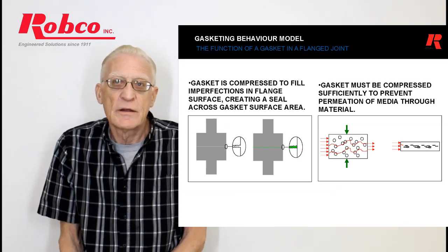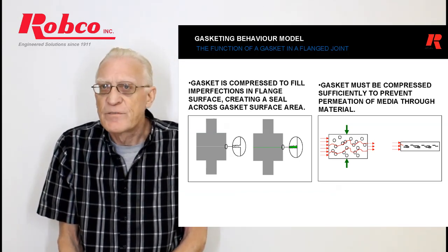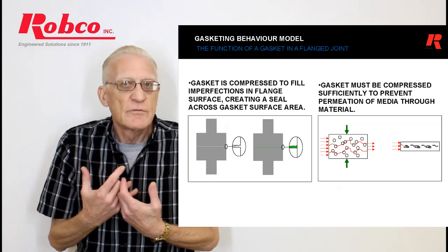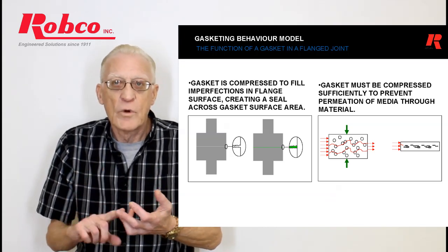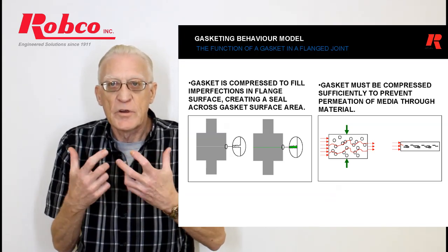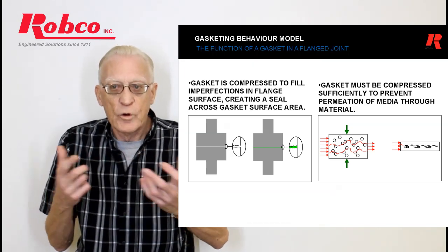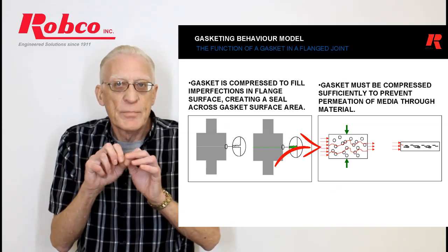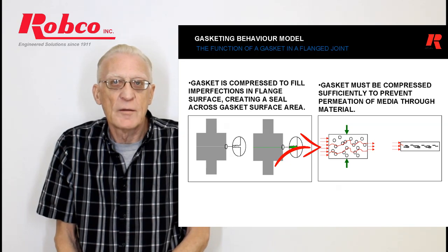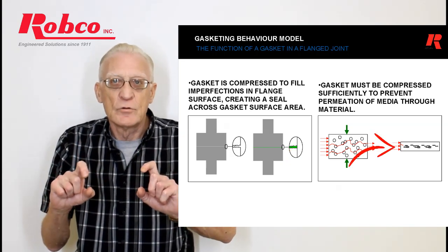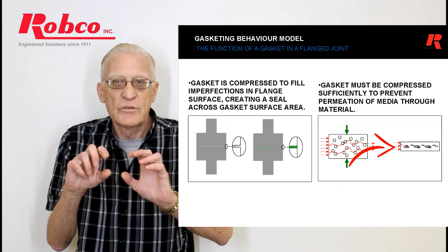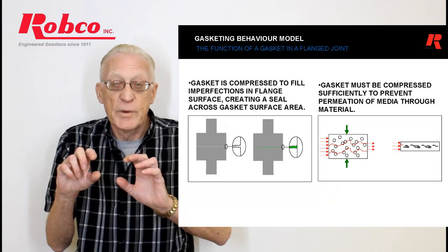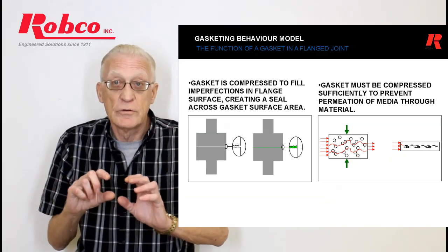Gaskets are also designed to densify, to compress. I'll take 2 steps back. A compressed sheet, for example, is a mixture of fiber, rubber, solvents, becomes like a putty that is formed into a sheet on a calender. Therefore, there are tunnels or capillaries of leakage paths through that material itself. When you compress the sheet down, you're trying to close those capillaries or tunnels of leakage, and you achieve it to a certain point. Asbestos, of course, was a rock, so it took a lot of load to close down